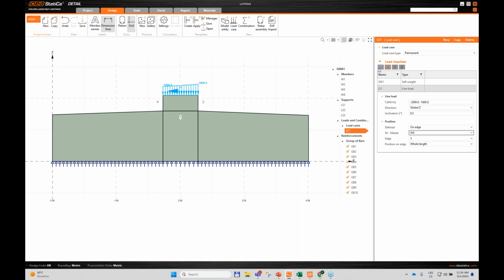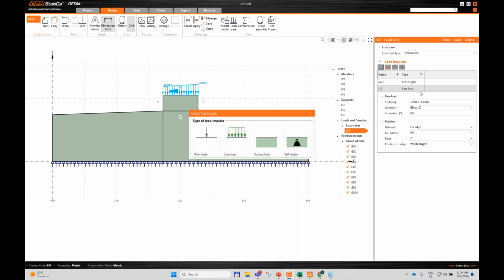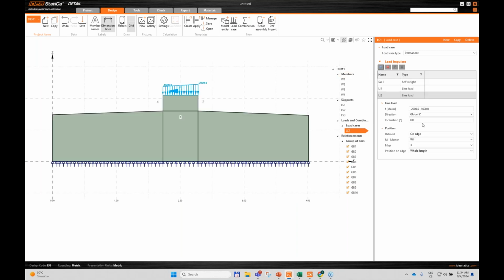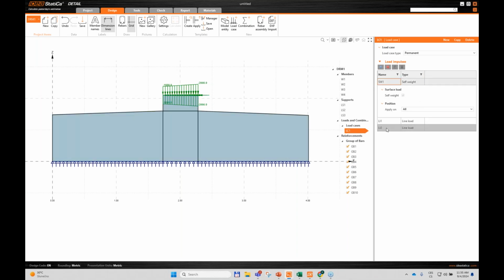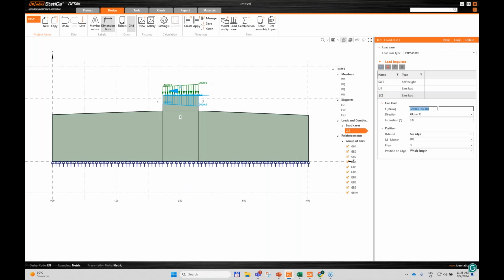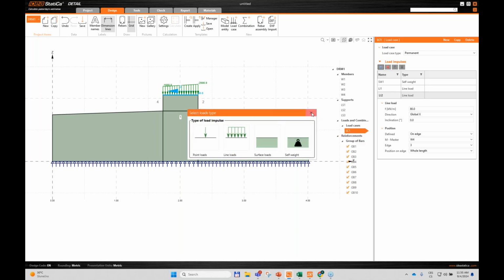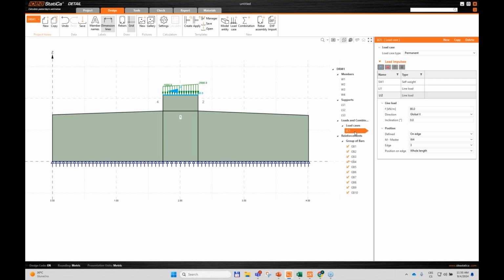The same way, I can input also the shear load. This time it has to be in the different direction, and again it's only the force divided by the dimension, so it's recalculated for my solution like this. Okay, so my permanent load is done, and I will do the variable load in a similar way.